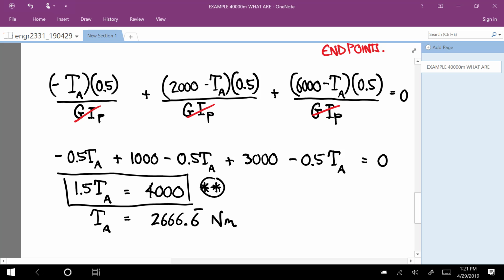Are we going to get anywhere where we actually have a Poisson's ratio for the shear modulus? Yeah. You'll do some problems like that. And if it's ever not given and you're dealing with metal, just use 0.3. That's the best guess.